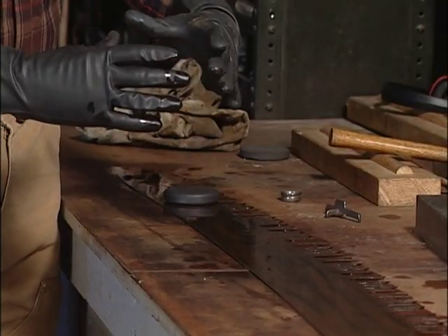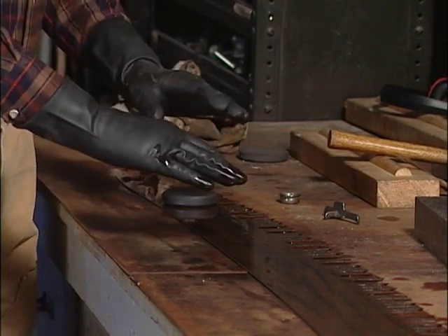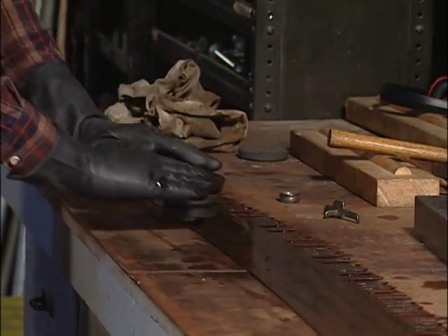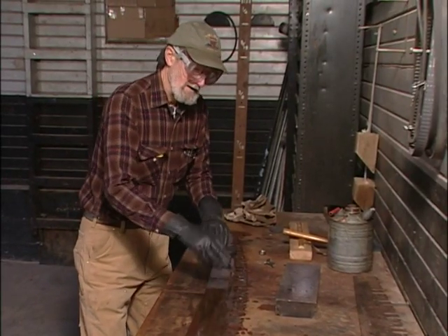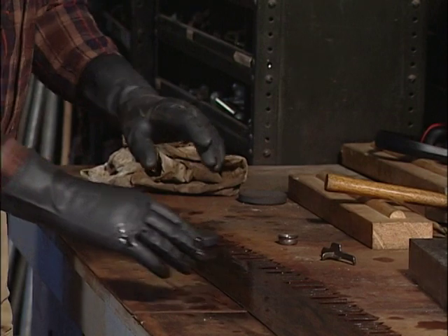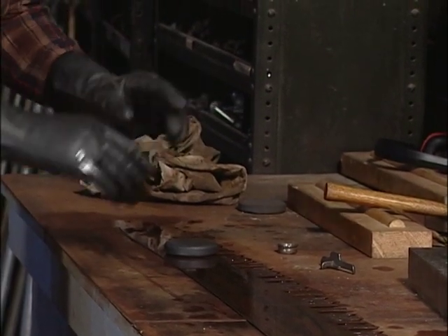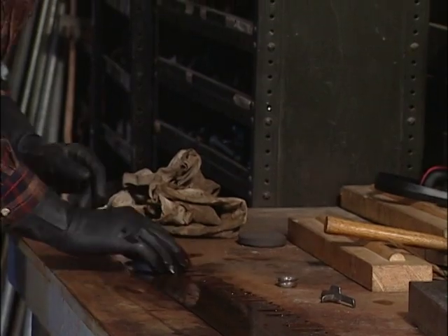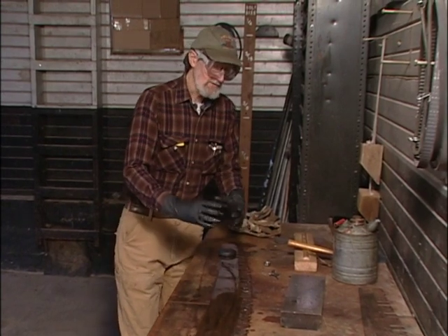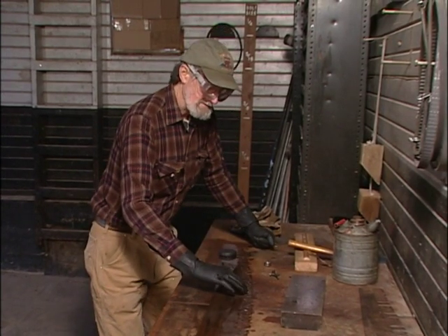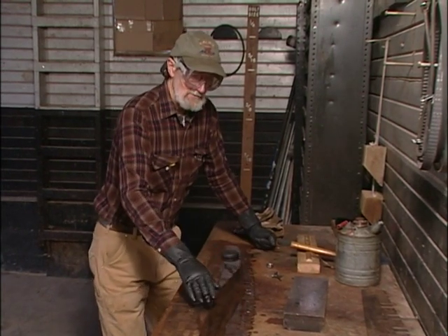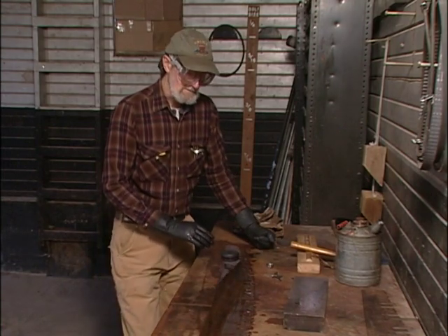One of the issues with an angle grinder or a rotary grinder is that unless you move the tool evenly back and forth on the surface of the saw, it's really easy to make dig marks in it, to actually dig right into the surface of the saw and put divots in it. So if you're using a power tool like that, either a belt sander or an angle grinder, be really careful to stay away from the tips of the teeth and use a fine abrasive so you don't unduly etch or scratch the surface of the saw.